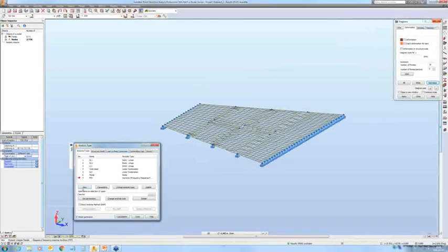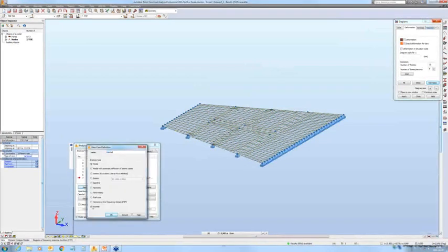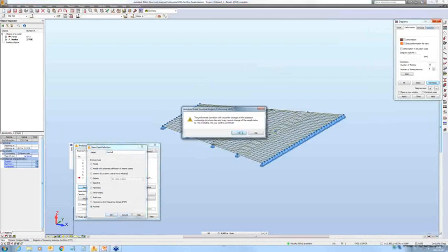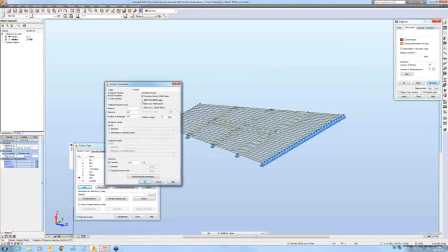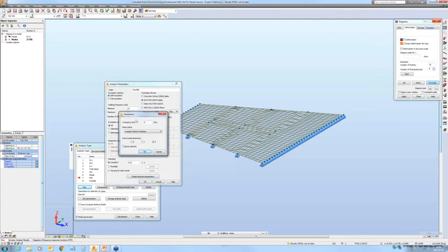Okay, I will define a new load case, footfall analysis. What I'm going to do, I'm going to select the code, SCI P, self-excitation, and I will select the damping as being 3%, and I will go to modal analysis parameters and set the frequency limit as 15 Hz.